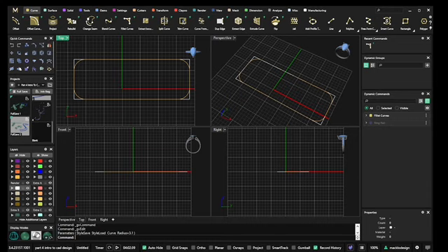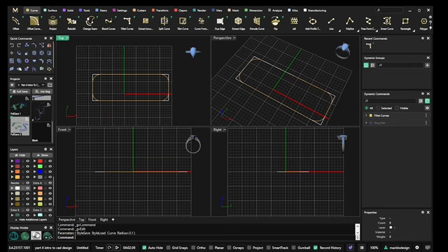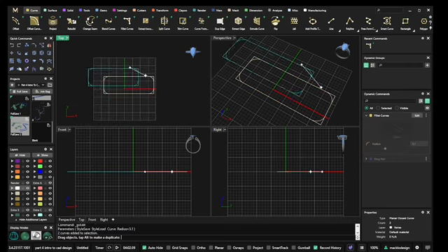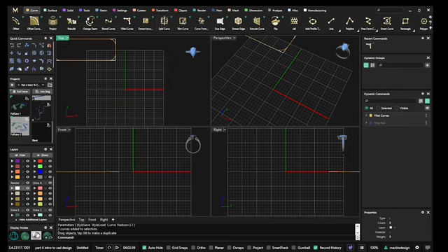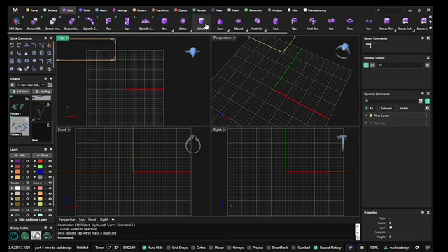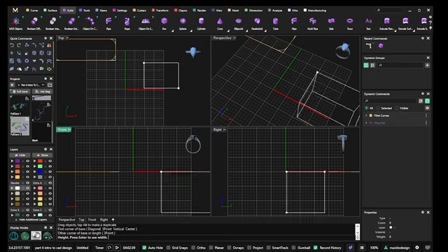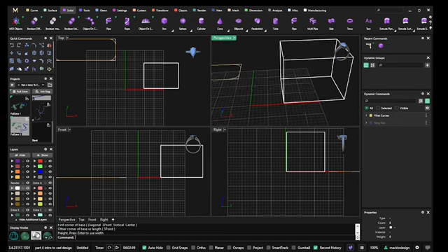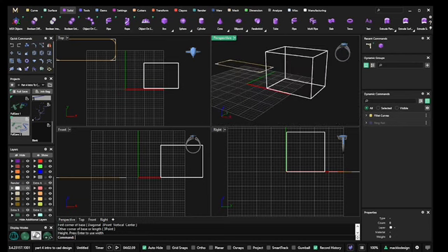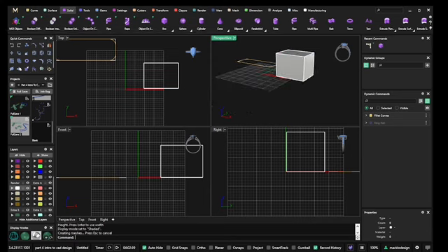All right, moving on. Extract ISO curve. I'm going to move that out of the way, have it still there. So in order to extract ISO curve, I am going to put a solid in the display. And I'm going to change it to shaded by right-clicking on the perspective title and clicking on shaded.